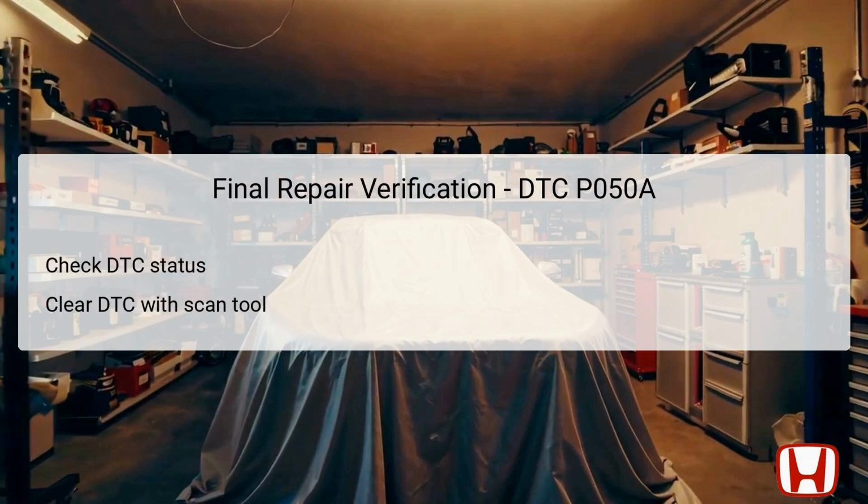Once all necessary repairs and replacements have been conducted regarding the components influencing the DTC P050A, it is crucial to perform a final verification of the repair's effectiveness. Begin by checking the current DTC status through the vehicle's diagnostic tool. If the DTC P050A is present, additional evaluations may need to be conducted on sensors or components that weren't addressed initially. If the DTC has cleared, it indicates that the issues have potentially been resolved.